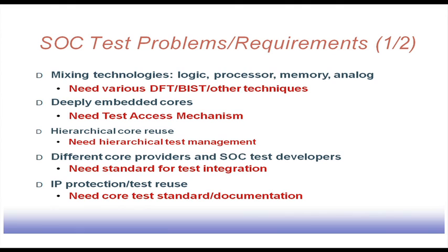Some of them may have a particular type of scan chain configuration. So, from the outside world I have to feed those scan chains with proper patterns. So, the requirements change. So, unlike a design which is done in house and done by a single designer, here different core vendors have their own DFT, own BIST and all those things. So, bringing compatibility is a big issue. So, from the outside world we have to add some extra thing into the system, so that the whole thing becomes compatible and the test sessions can be run.